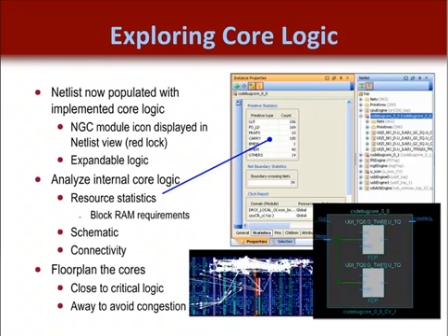The size of each of the debug cores can be easily found with the PlanAhead flow, but also can be found with other flows. Since the cores are added as netlists, given the file extension of NGC, they can be selected and their size determined easily. This is important because the amount of resources will vary by the number of match units you're sampling. Verifying the size of any component or netlist is normally done by right-clicking a component in PlanAhead. This will automatically generate a GUI like you see here, where the number and type of each resource contained in the component is listed. However, PlanAhead will also show you the connectivity of each core in a schematic.